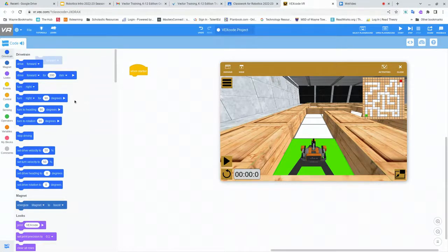So we're not going to use a plain drive forward command. We're going to use a drive forward command involving a set distance. It's really important that you make sure these codes snap in place just like you do in Scratch. And what we're going to do for this is use millimeters. You do have the option of switching to inches, but when we start coding with our robots in real life, we're going to be using millimeters, so you're going to stick to millimeters.